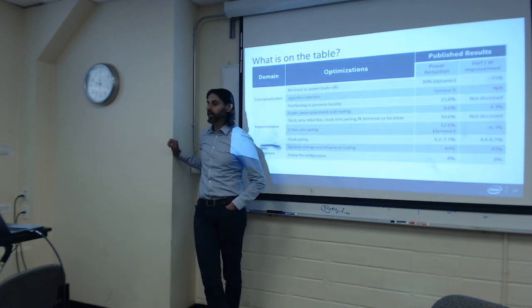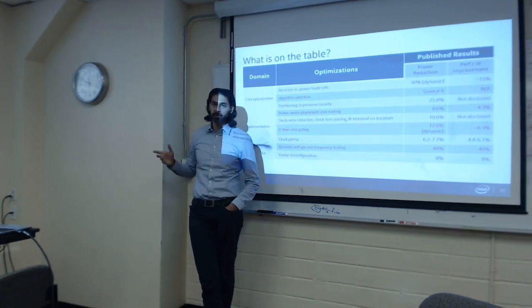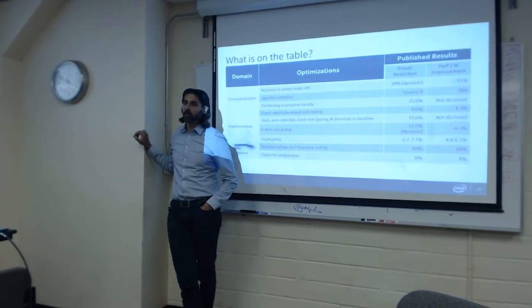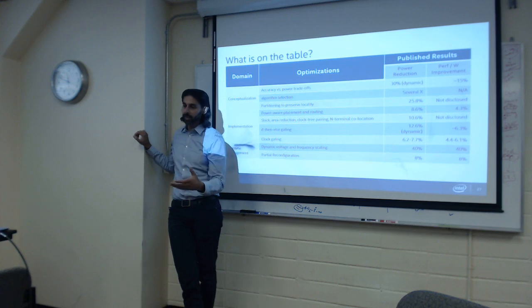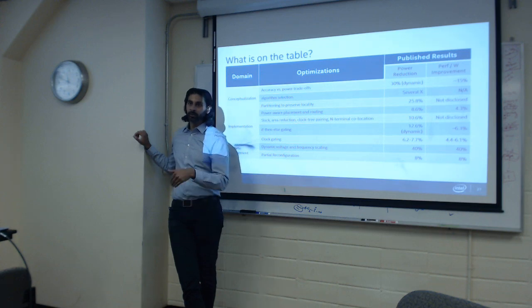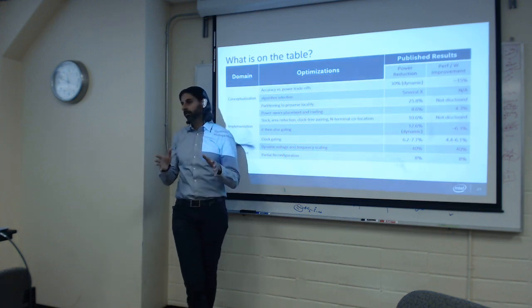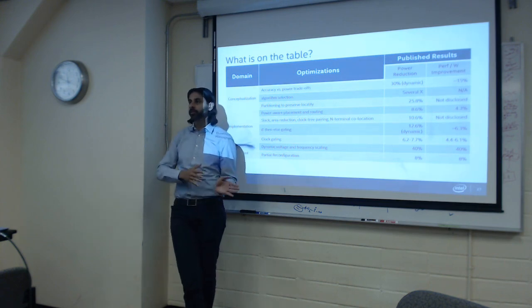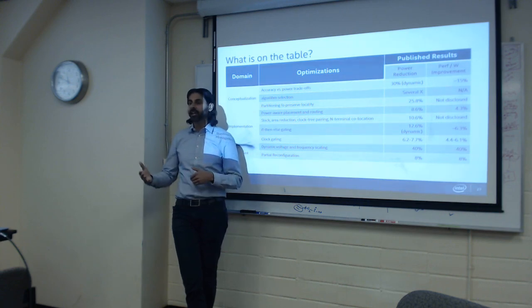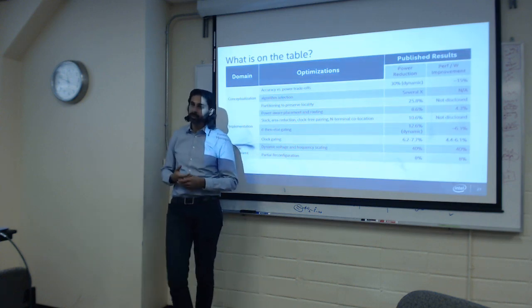So it's not that simple anymore. One of the features in Stratix 10, this is public information, is something called SmartVID, which means that at manufacturing time, the actual voltage that the FPGA requires is programmed on a per chip basis. So to power up a Stratix 10, you need a smart regulator that looks up what voltage this chip needs and then provides that voltage. The same application running on different chips would actually have a different mix of static and dynamic because the voltage is changing. So it's no longer safe to say static is always 50% or 40% or whatever it is. It actually varies part to part for the same application.